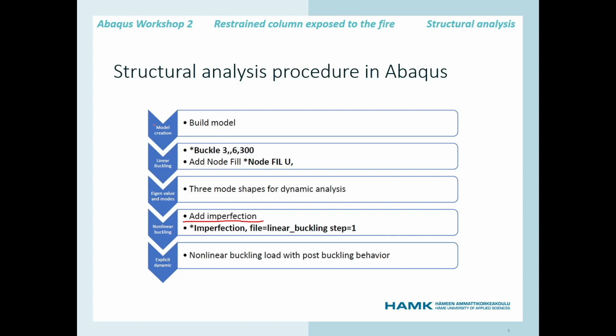First we create the model as we would for the structural analysis, and then we separately perform the linear buckling analysis, and we write this node file command at the end of the output request.